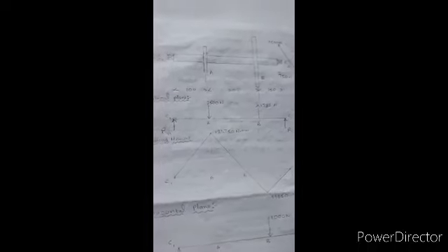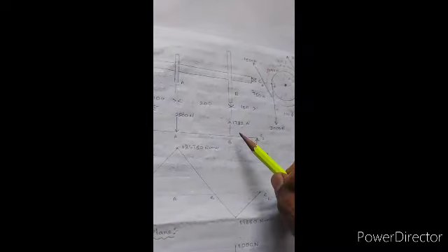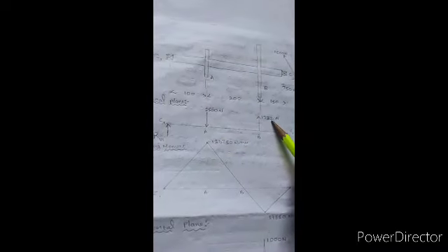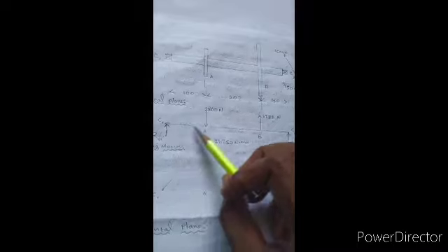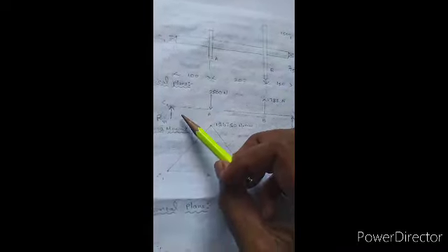Okay, I am telling you again, the vertical for 500 Newton is 433 Newton. Vertical for 1500 is 1299. Okay, so add both the values and we got 1732. Okay, so I have drawn the force diagram for the vertical plane. So in this vertical plane, two reaction forces were there, RV1, RV2, and one downward force 2500 and one upward force 1732.